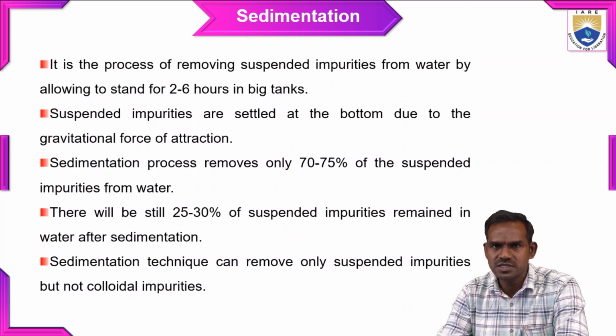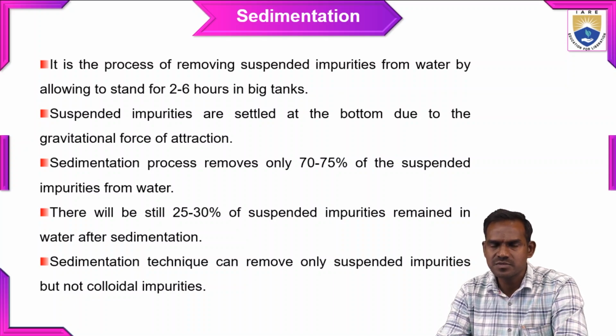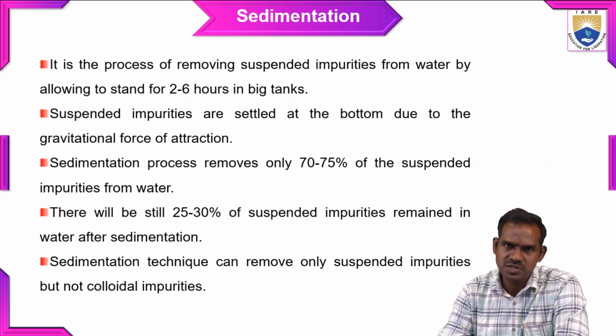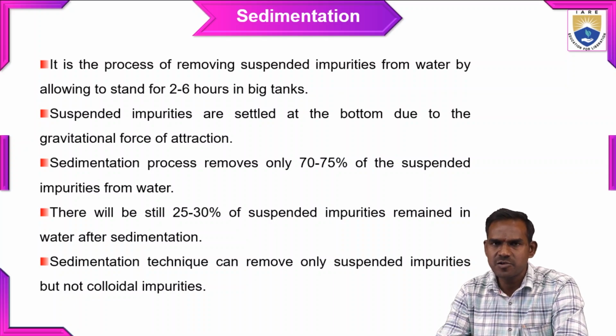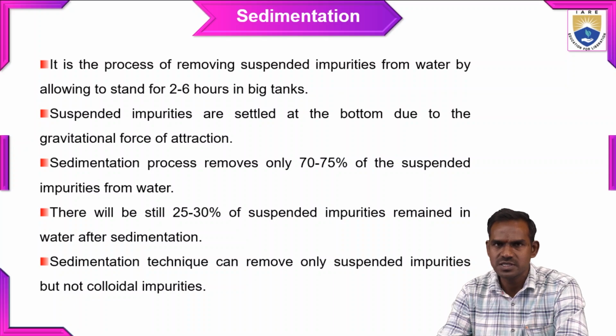Sedimentation is nothing but the process of removal of suspended impurities from water by allowing it to stand for 2 to 6 hours in big tanks. So the water must be allowed to stand. Stand means the water must be allowed to settle for at least 2 hours, maximum 6 hours. That is depending on the nature of suspended impurities.